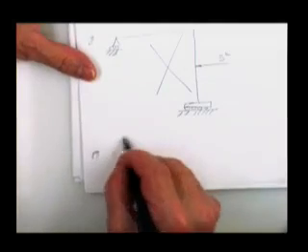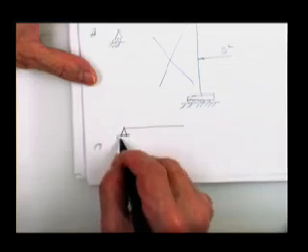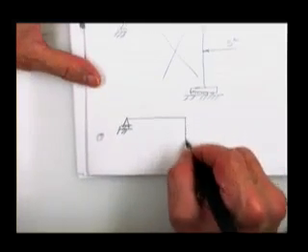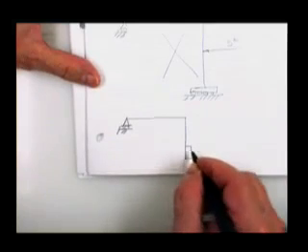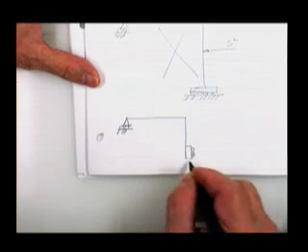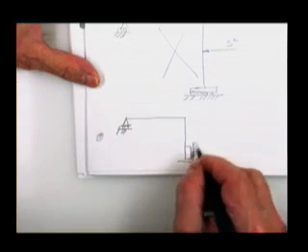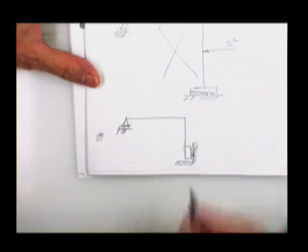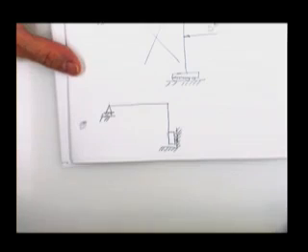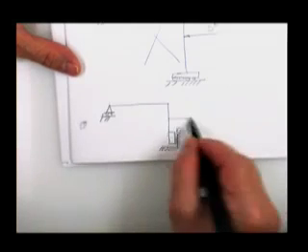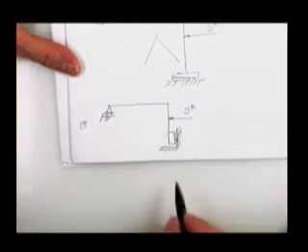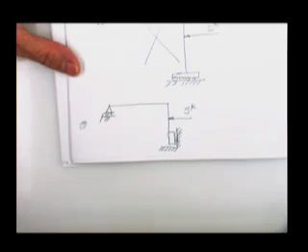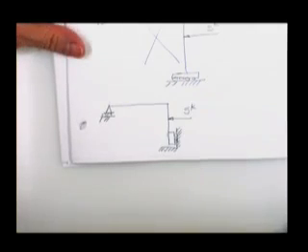One that would work, be weirder than all of them, would be leave that down here. Leave the ability to take moment, and leave the ability to take horizontal force so that the 5 kip load can be picked up, and then remove the vertical force. That one will work. I don't know how it would deflect. I wouldn't touch it with a stick. But it is anything that you remove one reaction and it doesn't make it fall down, that's an acceptable primary structure.